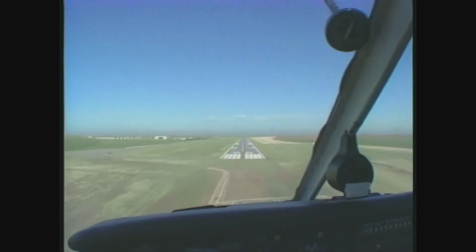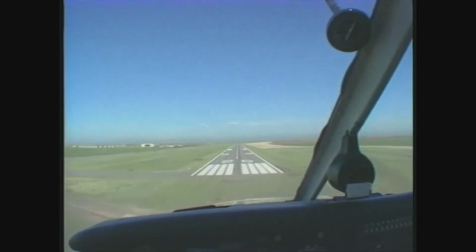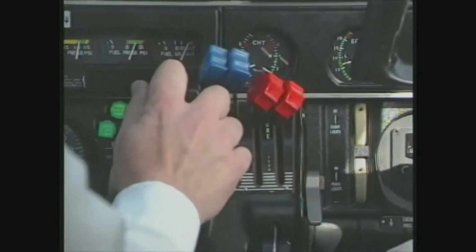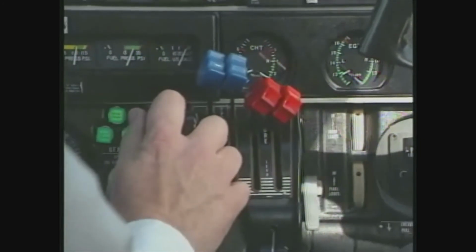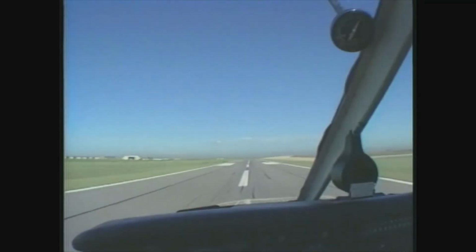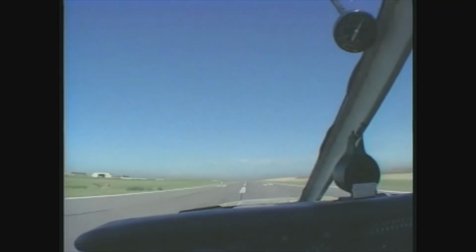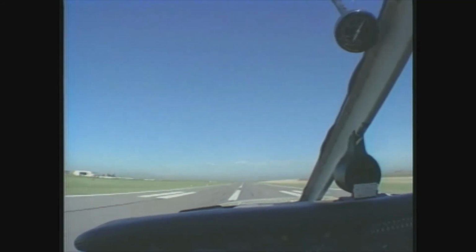This is very apparent on final approach just prior to touchdown. If you retard the throttles rapidly, the loss of lift may cause a high sink rate. Induced airflow is one reason you should carry some power throughout the approach and smoothly reduce it during the flare and touchdown.